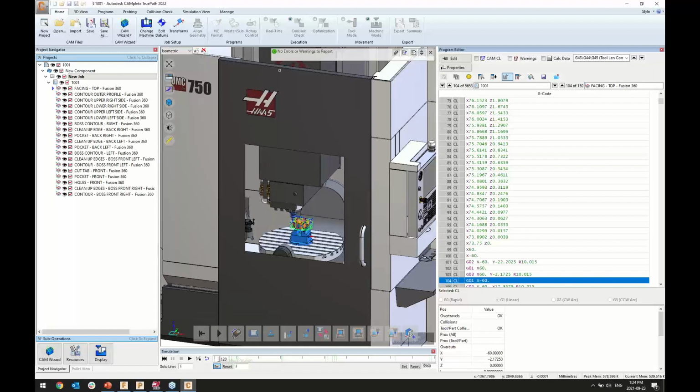So at that point, would there be no issues detected or anything to report, we can literally export the G code, get the setup sheet that goes with it, and take this code and go put it on the machine and have the assurance that everything will be running as expected. So that would be a very straightforward workflow to go, for example, from Fusion 360 to having G code. This is a very simple operation. We'll simply use the CAMplete app, click post, everything gets transferred, we pick the machine, and we have G code. So to get to that point, very straightforward.